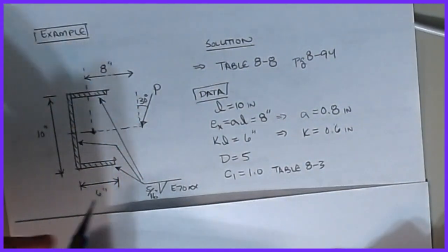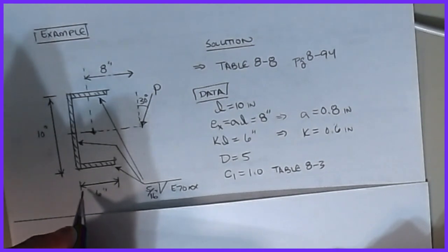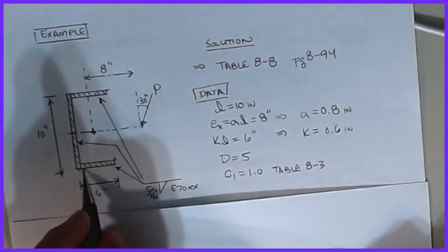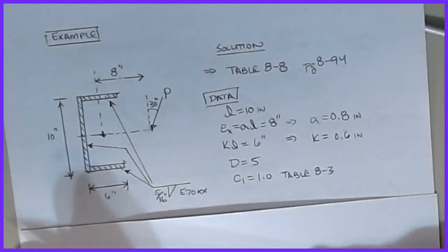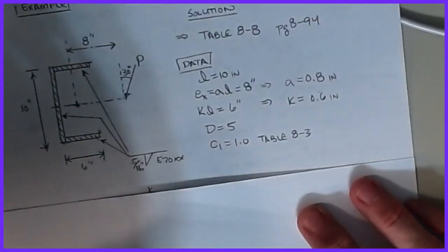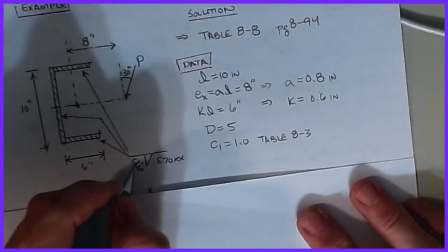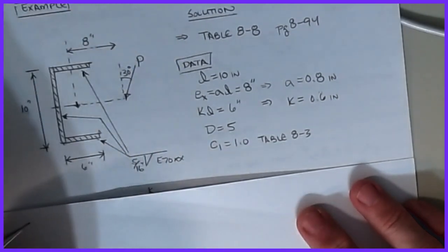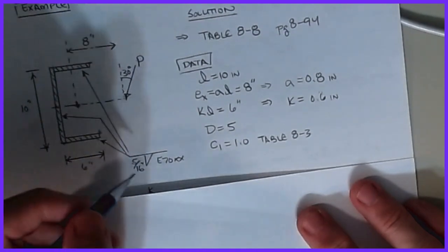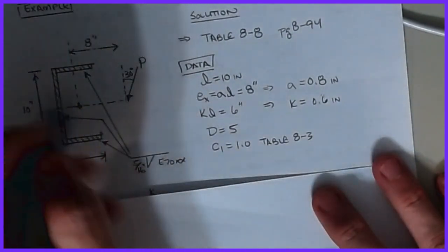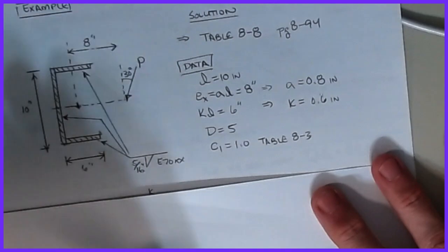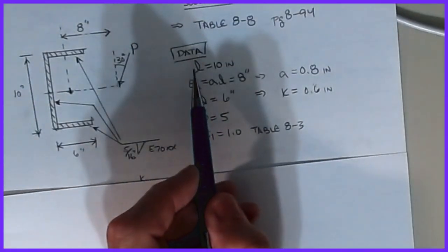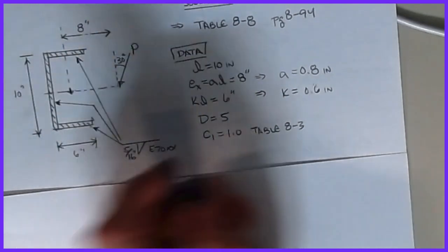And so when I do this, and we go in, I missed one. Oh, the 6-inch, yeah. The length of this weld is 6 inches. Okay, and then we've got our weld symbology that basically says that all three of these are 5/16 inch fillets of E70XX electrodes. And so that should be fairly clear what we're doing, and that's kind of how we can denote all the weld symbology for this.